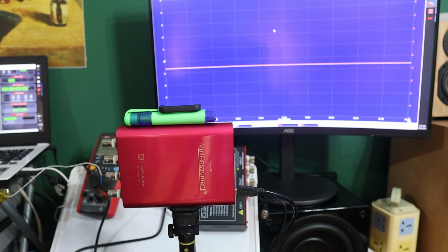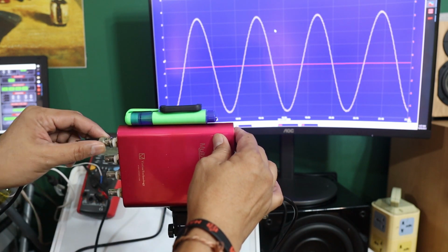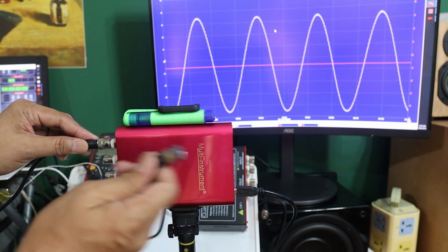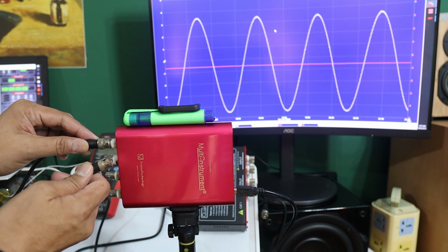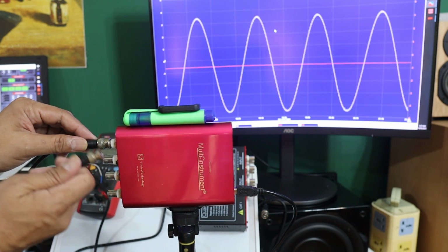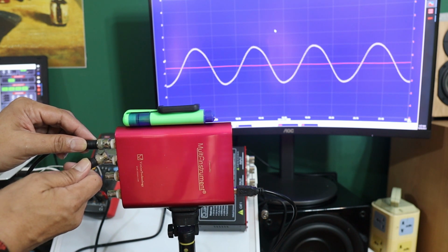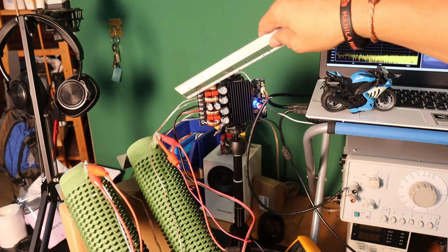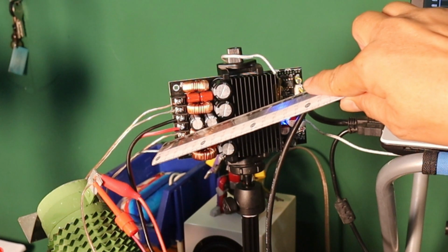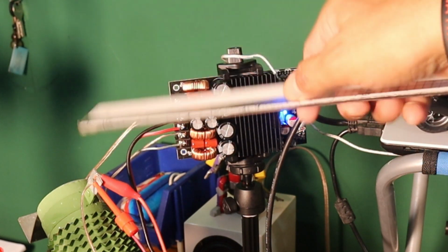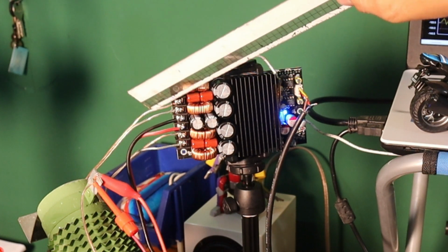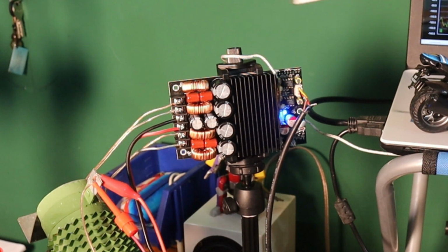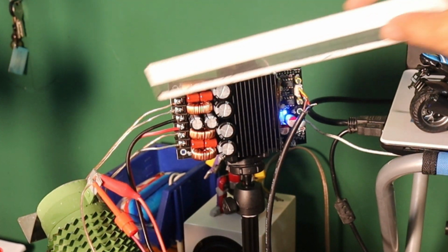I can use the right channel actually if you'd like. That is the capture from the right channel right now, and this is the left channel, and you can see what is going on. I just put it into the supposed reference ground. I suppose that the connection on the board, I call this one the left channel and this is the right channel. So you can see from the speaker wire we get, I can say this one is a live one and this is the GND. That is evident for SE mode, that is the single-ended mode.